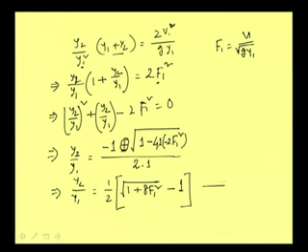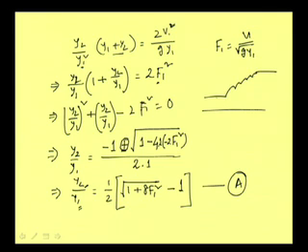So, this is the very popular expression for relating y2 and y1, which are the sequent depths of a hydraulic jump. This is y1 and this is y2. In free flow condition, the jump will just start from this point where the depth is y1, and it will end at this point where the depth is y2.